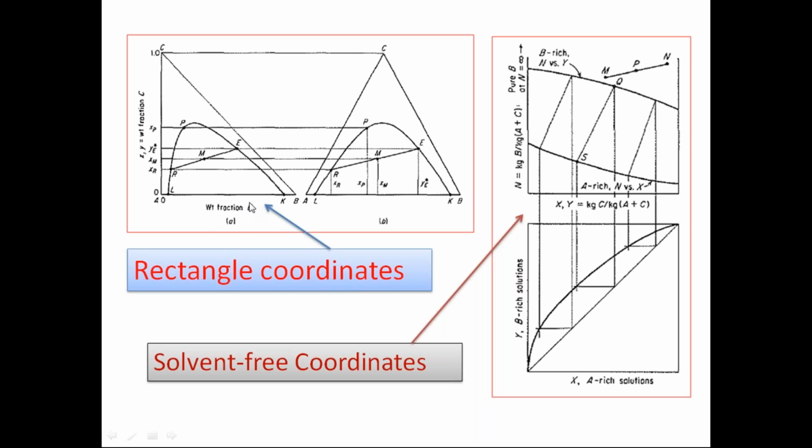What is B? B is the organic solvent which you are intentionally adding. So when you add at less quantities, you'll find the raffinate phase, and when you add more, then you find the organic phase. What you have to do is, when you are adding a certain quantity of B with the feed mixture of A and C, it may have a homogeneous phase, and as you go on adding the B, the homogeneous phase will turn into the heterogeneous phase that you can observe. So that point you have to note down.